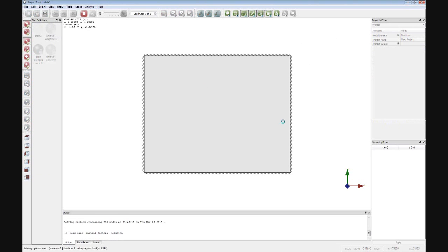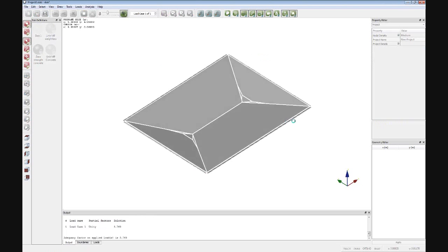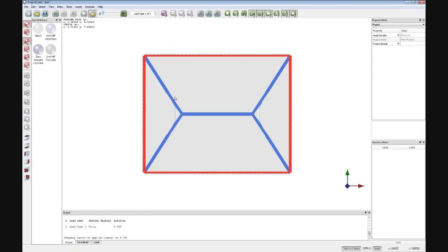And then if I solve again, what we'll see is that actually we get the envelope failure mechanism again, but what's happening in this case is this horizontal section in the middle here is expanded out, so the triangles at the ends are smaller, so obviously that change has had an effect on the problem. And also you can see that the solution now has gone up pretty much threefold, from being 1.22 to being 3.77.